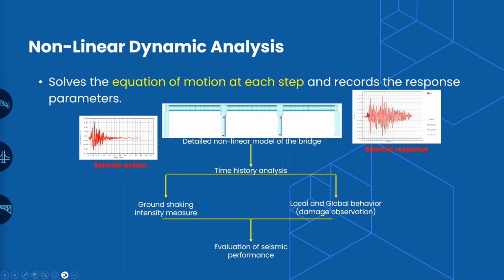So you can see that it is varying and it is not constant. In pushover analysis, we used to get one single value for the analysis. However, in the time history analysis, we get a record of the response of the structure with time, and generally the peak response of the displacement or the peak response of acceleration could be considered as the governing characteristic for that particular time history application.